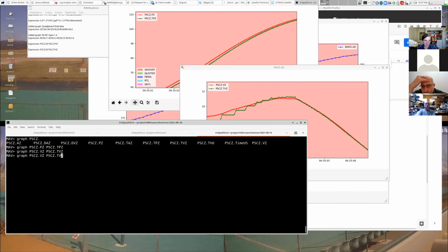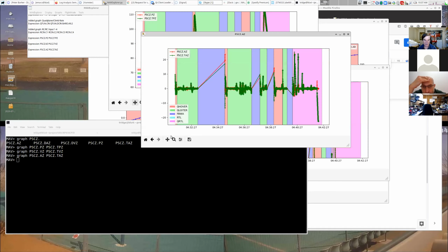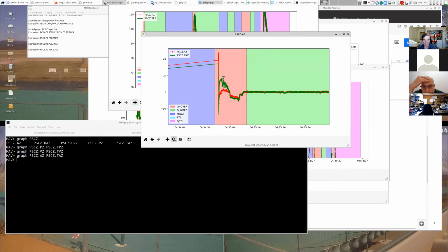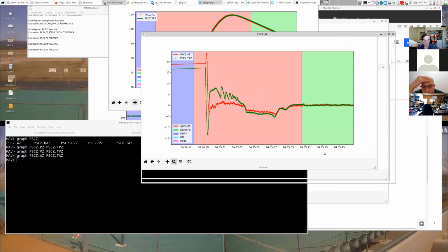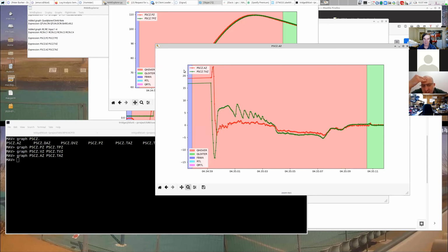Okay, let's have a look at our accelerations. Vertical acceleration, so AZ, which is our vertical earth frame acceleration, and our target acceleration. Let's go back and zoom in again on this part. Now, there are a few things that are interesting here. First of all, we see these numbers are in meters per second per second. These initial numbers here, that's 2G. That's a lot for a plane going from forward flight to vertical, it's going whoosh.